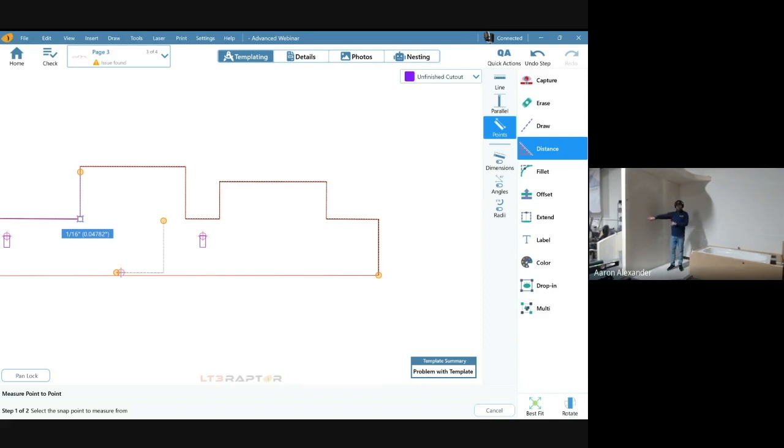Once you shoot that wall, check it all, get level and plumb on it, because we know we're going to install the back wall plumb. So you better cut this edge on this wall plumb in space, or else that really ain't going to line up with the back wall you installed. If you've ever had that issue, that could be what happened right there.